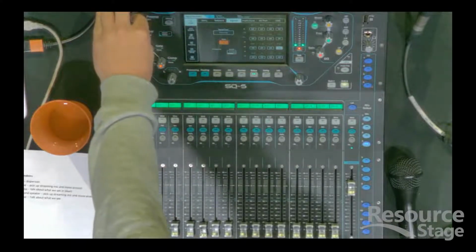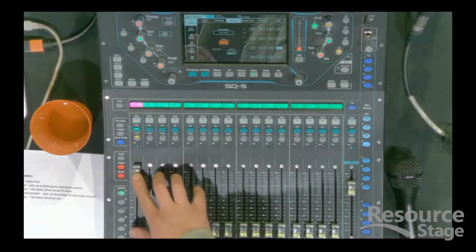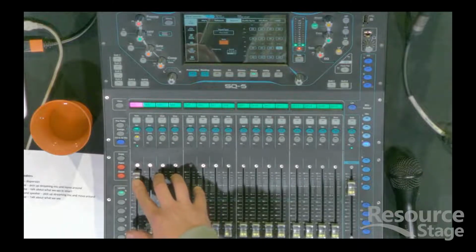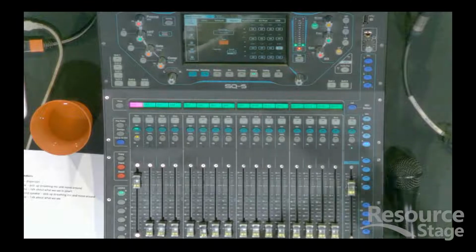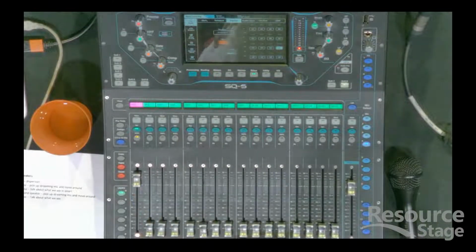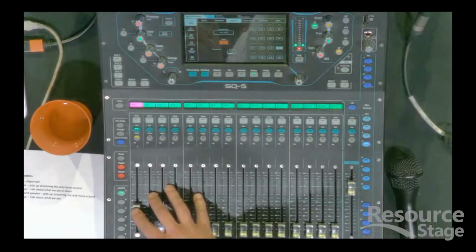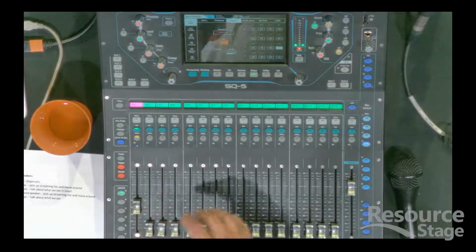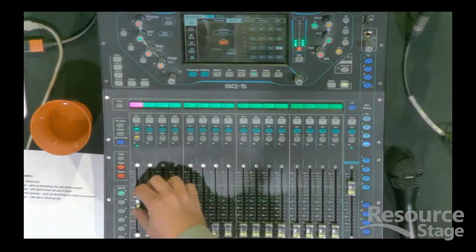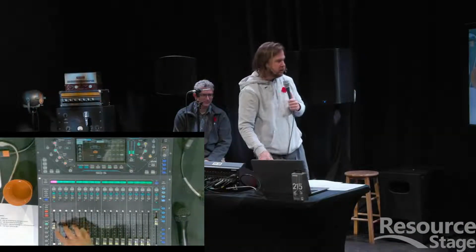If I were to bring down my gain, so now we can see it's quite low on this meter. I have now limited my ability to mix this microphone to this range. And as I mentioned before, this problem can add up as it goes to the next piece of equipment, to the next piece of equipment. If we go to the opposite issue, too much signal coming into the microphone. Now I have the similar issue where I can only move my fader a small amount. So moral of the story is get the input right and you'll be able to operate the equipment as it's designed to.